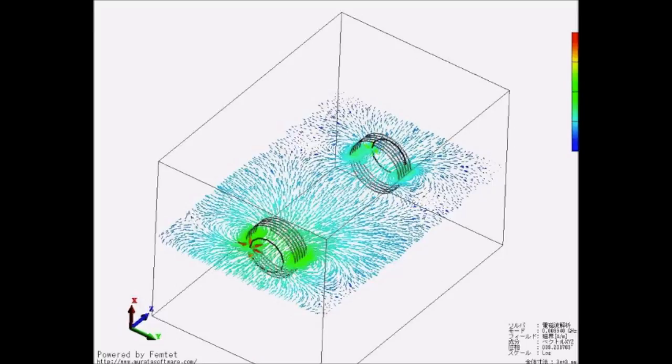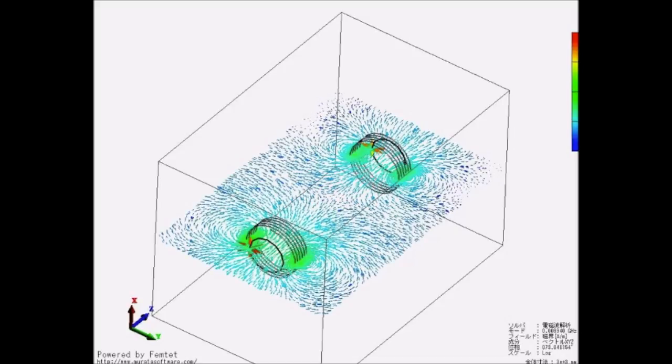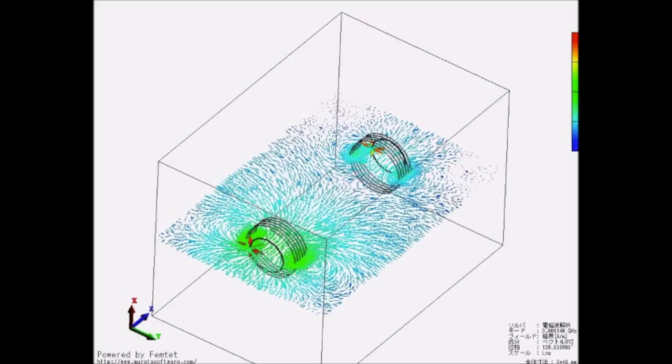To conclude, the main voltage is converted into an alternating current signal, which is then sent to the transmitter coil via the electronic transmitter circuit. The alternating current flowing through the transmitter coil induces a magnetic field which can extend to the receiver coil, which lies in relative proximity. The magnetic field then generates a current which flows through the coil of the receiving device.